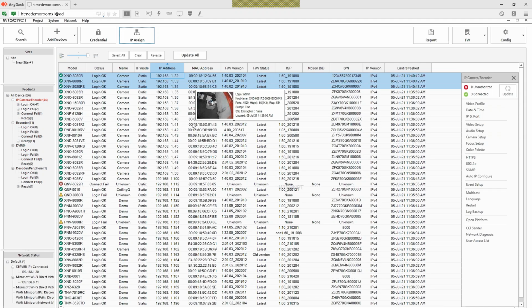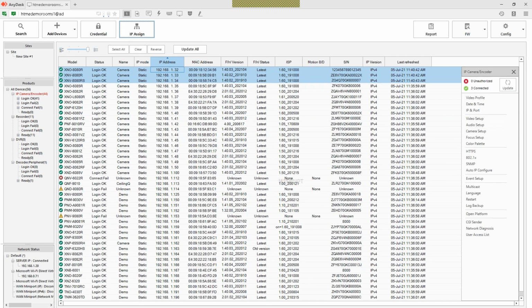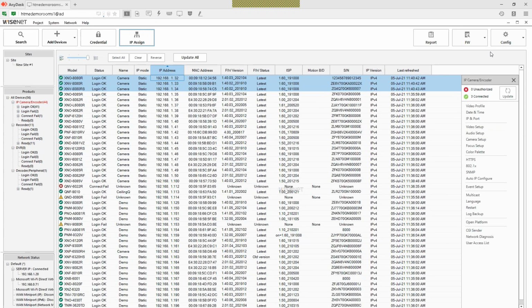Okay, what is next? Next is firmware update. You must make sure you update the camera before you proceed with the project configuration. Whenever you have a camera with you for the first time, make sure you update the firmware. It is a mandatory step. Not only camera, if you have NVR, you must update the NVR also. How to check if your NVR or camera is up to date or not? You can check it from the device manager by clicking firmware status check.